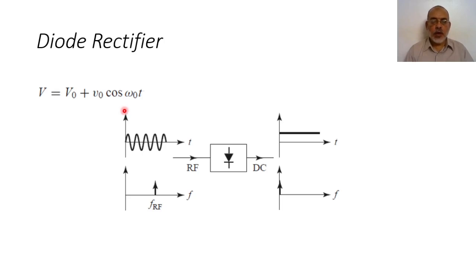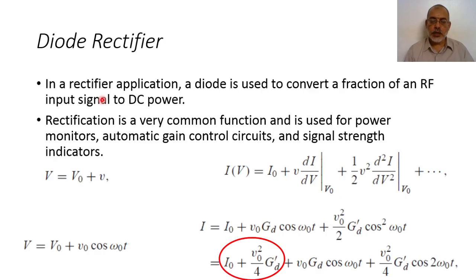Effectively, it is quite similar to the case of a rectifier at low frequency, but the situation here is different because the harmonic in this case is at higher frequency. So if the junction capacitor is slightly large, the harmonic will pass through the rectifier and the output will be mainly AC. So in this case, we are just rectifying the signal to obtain a DC component proportional to the input AC signal.